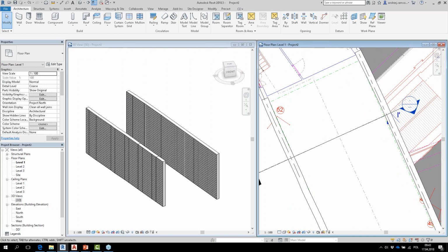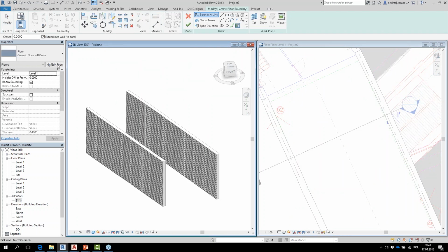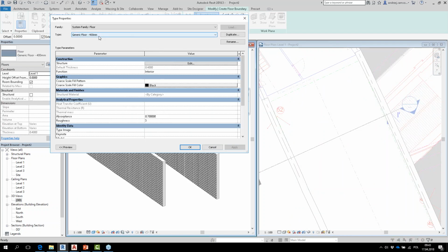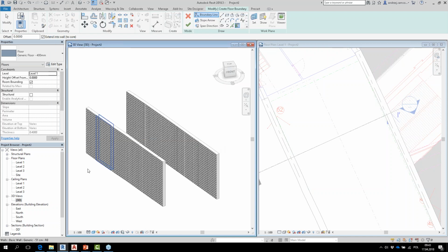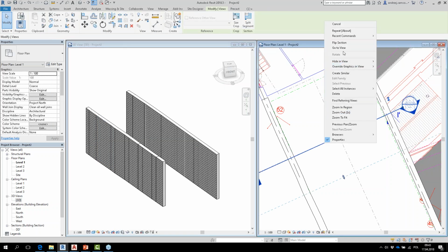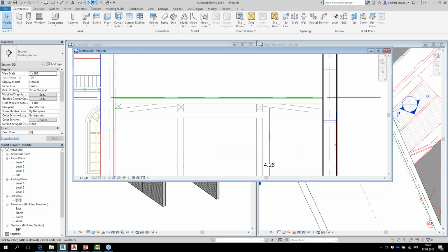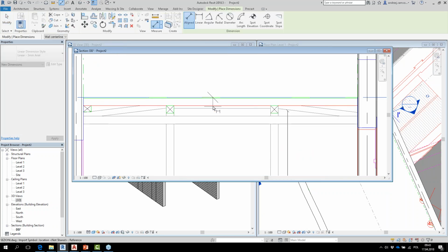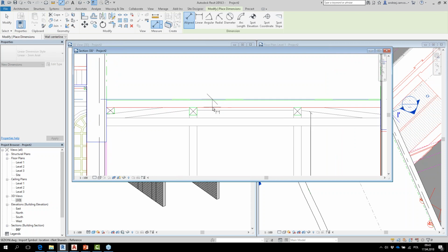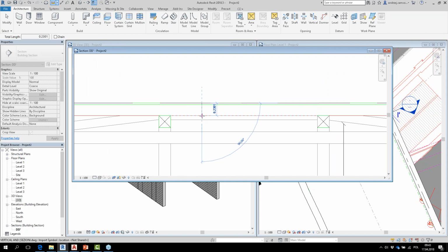here, so you can understand that we don't have to just create something like walls, but also floors. I'm gonna click floor architectural, edit type, again floor 400 millimeters. Maybe I should have measured the thickness of my floor before. Go to view. So this is a wooden floor. Let's say that I will consider up to here, right? Oh, it's not 0, it's because the scale is too small.